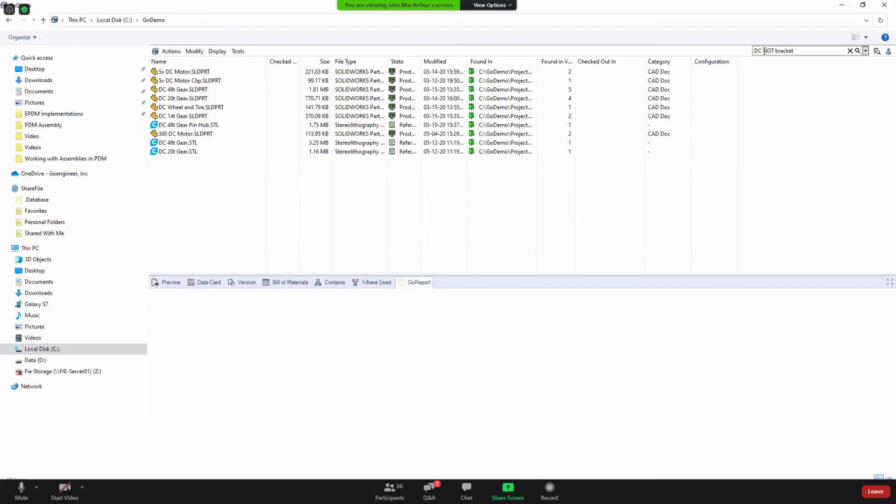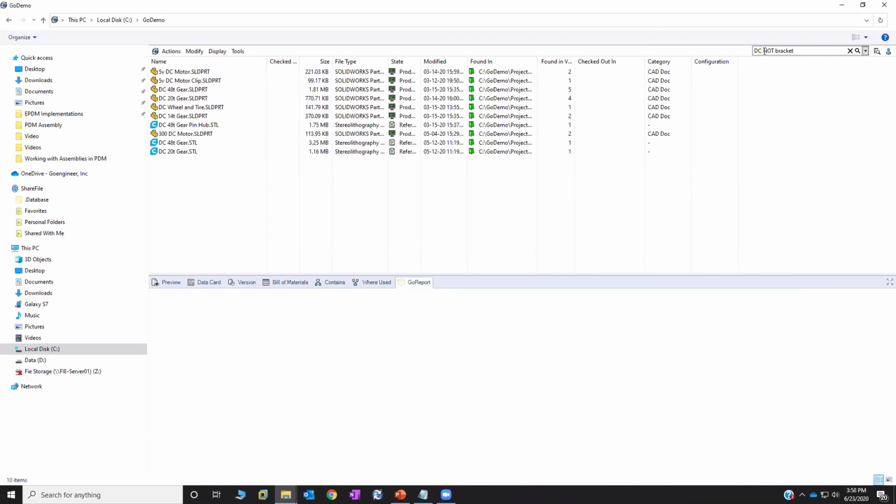The one danger that you risk is if anything goes wrong with the local view, if it needs to be recreated, those files can get what I call orphaned. An orphan file is not lost, but it is no longer really attached to PDM. So you have to copy it out, recreate a local view, and then overwrite to get it back in. But I've not really had a whole lot of problems with local views lately.